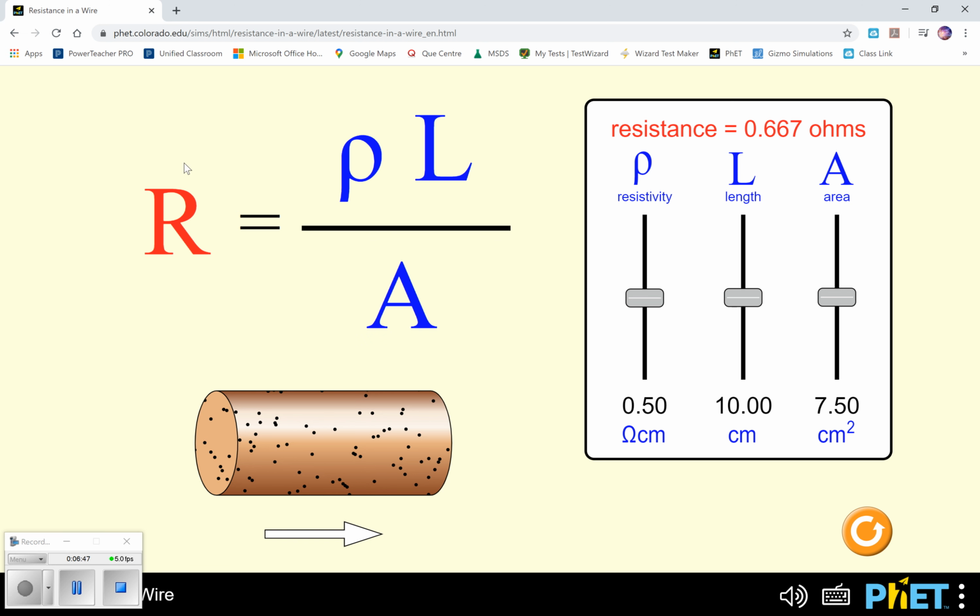And we'll see this shortly, once you have more resistance in a wire, the longer that current has to flow, the more resistance, and that's going to cause more heat. This becomes a fire hazard using really long extension cords to run heavy-duty machinery. It can cause cords to melt as they heat up from all the electrons that are moving through that conductor.